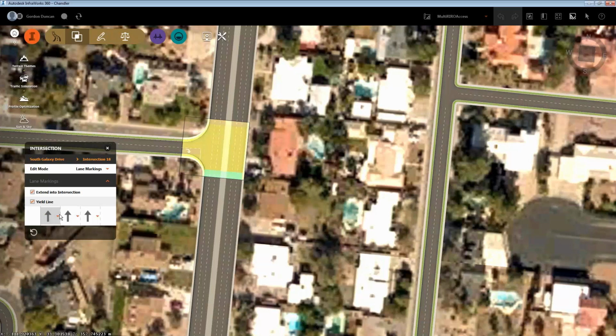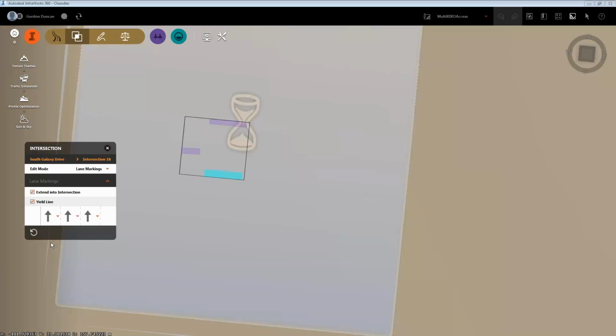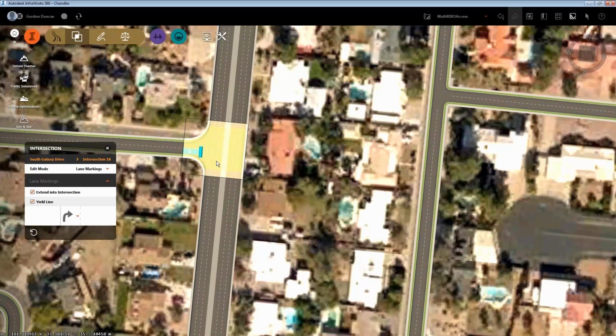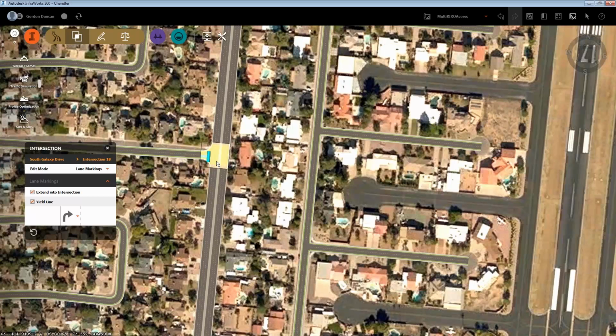So if I go on this one, there's 3 lanes going in there, say a left turn is possible. You can see that by doing that I've opened up the median, and that's no longer right in, right out. So if you make sure that there's no left turn allowed there, and also similarly in this one, that only a right turn is allowed there, then you get a right in, right out intersection, and that'll be modeled correctly in the traffic model. So that's what we've done.